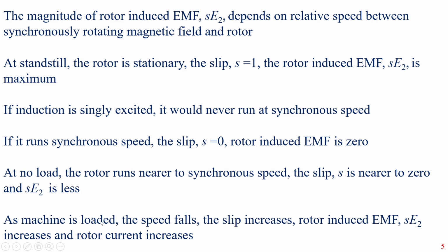As machine is loaded, the developed torque dominates load torque. The speed falls till developed torque equals load torque. When the speed falls, the slip increases, the rotor induced EMF SE2 increases, rotor current increases, and power drawn from stator increases.